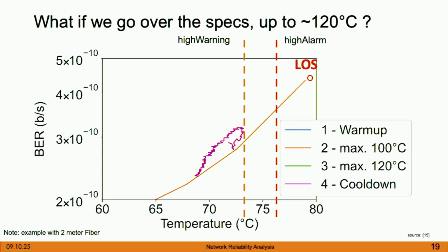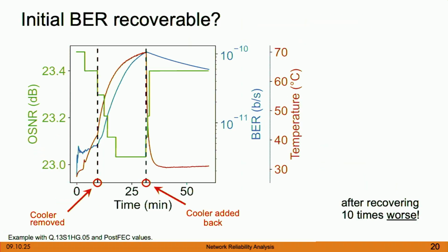And yeah, so I know this transceiver still recovers, but I wanted to see if it can go back to the bit error rate I had before, if I damaged anything with the 120 degrees. And it turned out after my cool down exercise, I still am hitting the curves of the previous one with 100 degrees. So this transceiver is still operational, works. And I think these are good news. But yeah, you shouldn't do this too often. Anyways, bit error rate, is it recoverable?